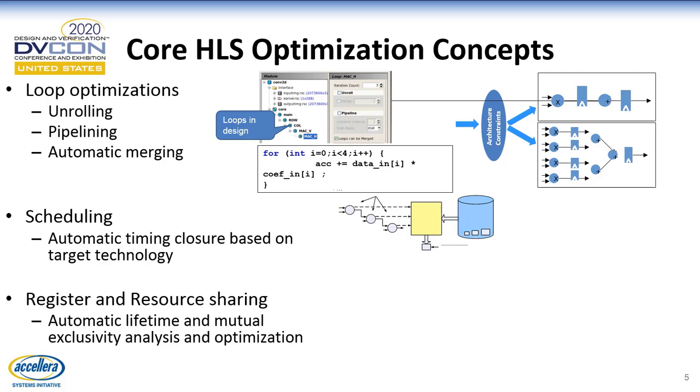And what the high-level synthesis tool does is it can automatically do this for you based upon the input directives that you hand to the synthesis tool. And you can actually do this type of exploration. You can do partial loop unrolling, and you can change the pipelining characteristics so that you can meet specific throughput targets for your implementation. And these types of transformations are quite tedious and take a long time to do in RTL, but they're quite fast to do in high-level synthesis tools.